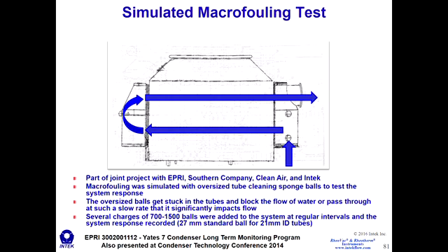And so let's take a look at some of the data from these single tube monitors and data from the DP monitors, which we highly recommend for quantifying macrofouling. Yes, this is a schematic of the condenser. There's the inlet here, inlet cooling water. It goes through the bottom half of the condenser, turns around in the back side of the condenser, and flows back through the top half.